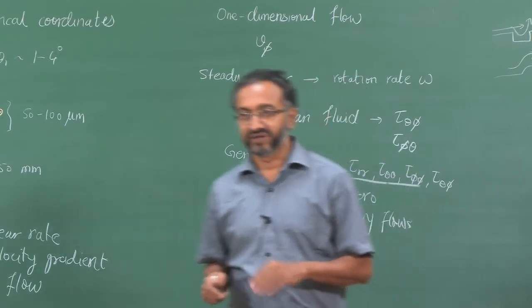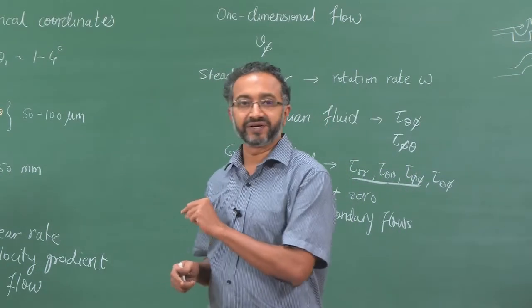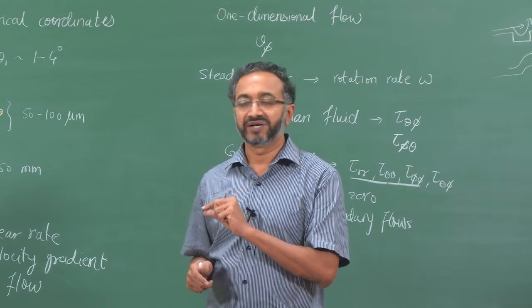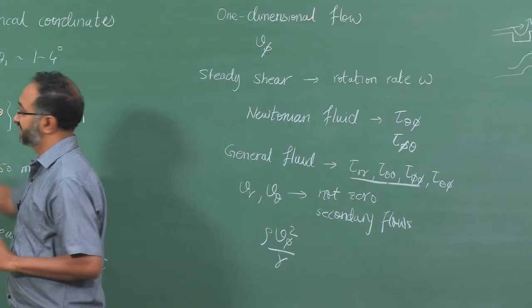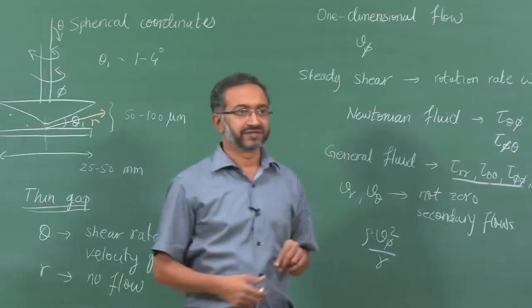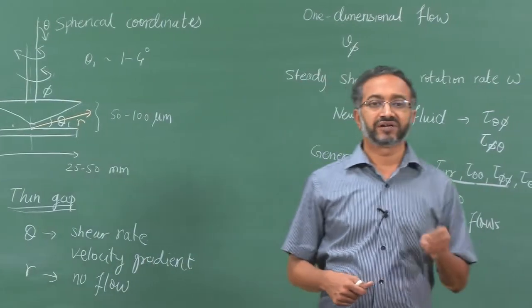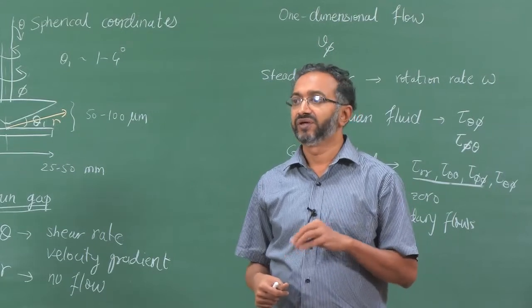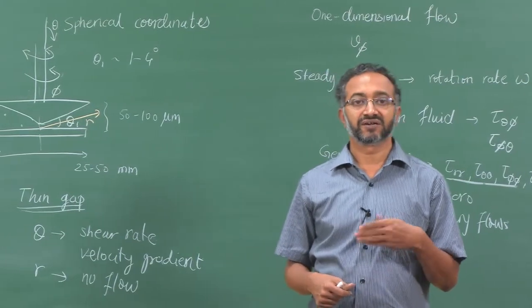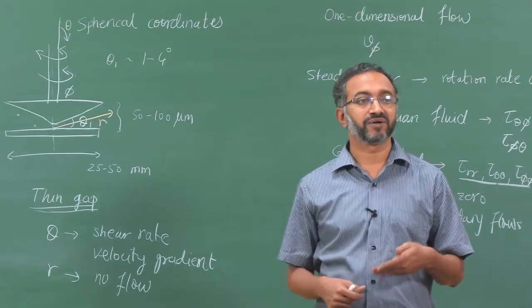And then given that we have many different types of fluids, depending on the nature of flow here, there can be local pockets of turbulence. For example, we know that in microfluidic channels, even though Reynolds number is low, it is possible to have turbulence at a much lower Reynolds number compared to 2000.